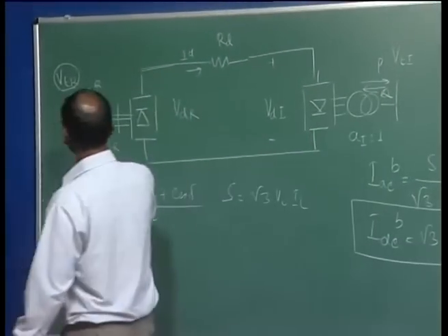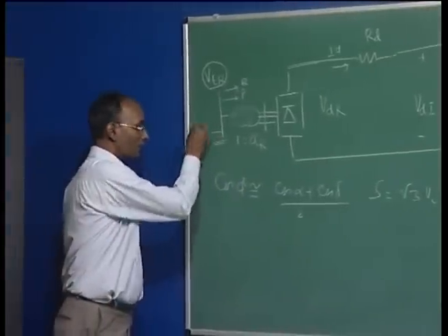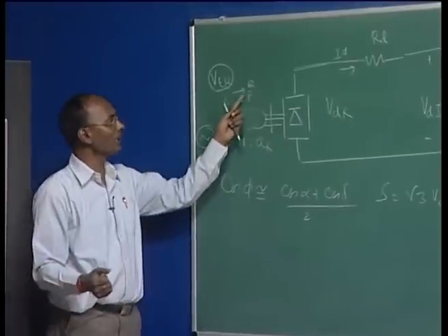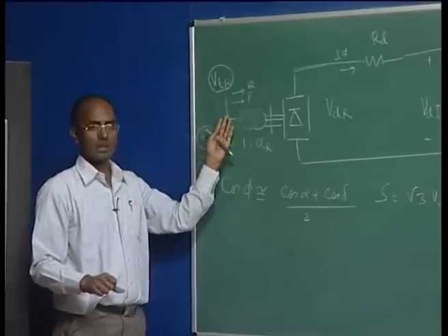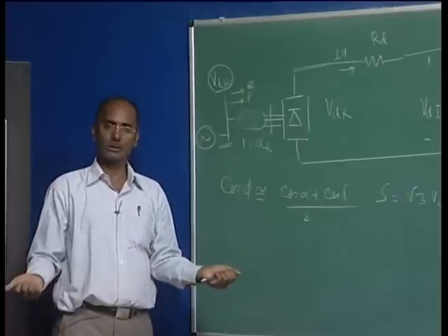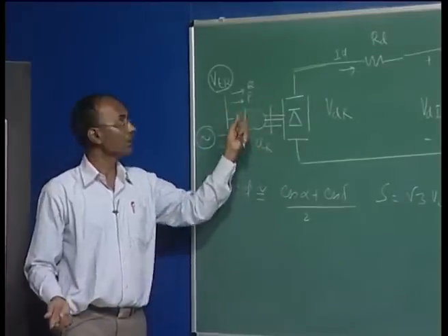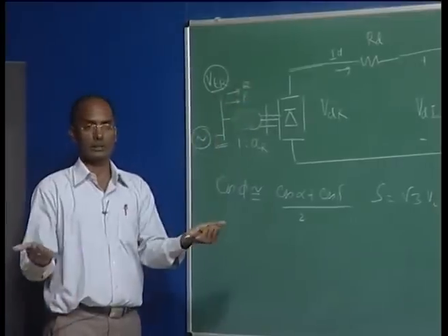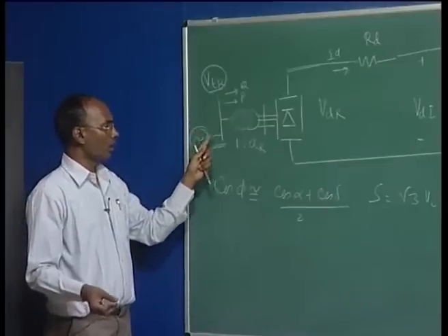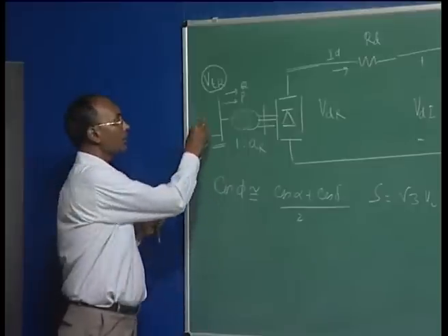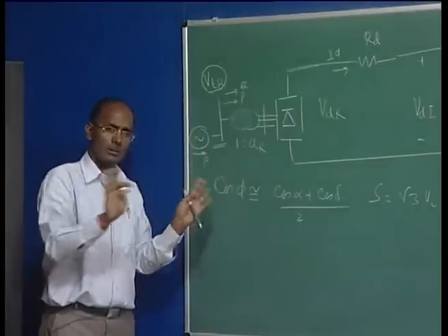Now here you can ask, what is this bus? It may be a generator bus, a huge generator, it may be hitting its limit. Again the Q you have to verify whether it is a generator bus or not. If generator bus, the voltage is the same, so this is a DC solution, no problem, because the voltage is maintained. The reactive power it is giving will now vary, the power factor will be changing, nothing else. In that case, P will be specified here. Whatever the P is going, you have to write the P equation in the AC as it is, no difference.